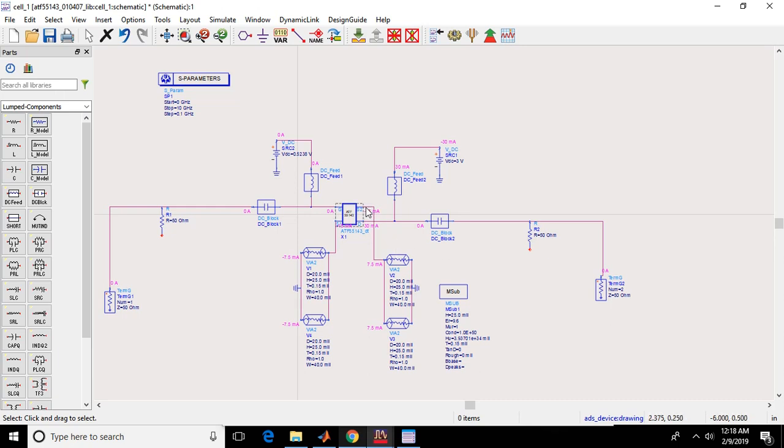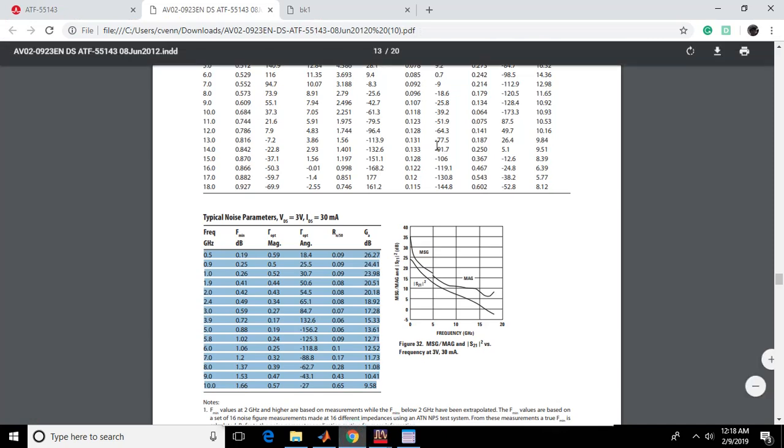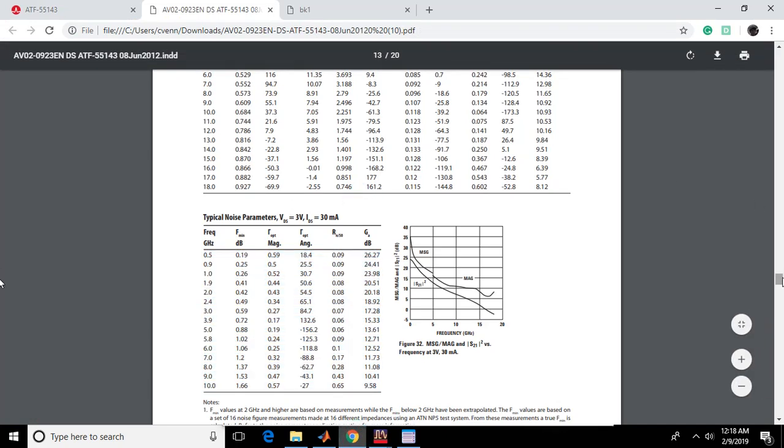You could also use extra transmission line here at the sources, and that's one reason why you would want to use an ADS model for your transistor, because that will make your S parameters a lot different than what they are in here.